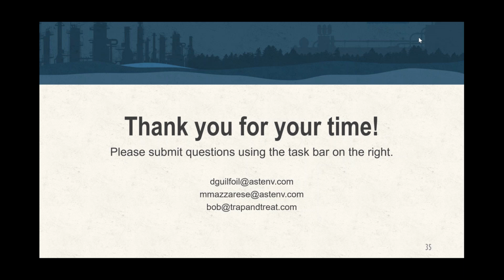Well, the samples should be discrete. We're talking about 2-ounce jars, and hopefully we're not going to composite a 1 foot section or say a 2 foot section out of a macro core. We're going to grab an inch or two of soil from 15 feet, for example. And because you are collecting such a dense quantity, if there are any outliers, they're taking a small sample when they get to the laboratory. If there's an outlier, then we can throw that out because we've got enough samples to base that decision upon.